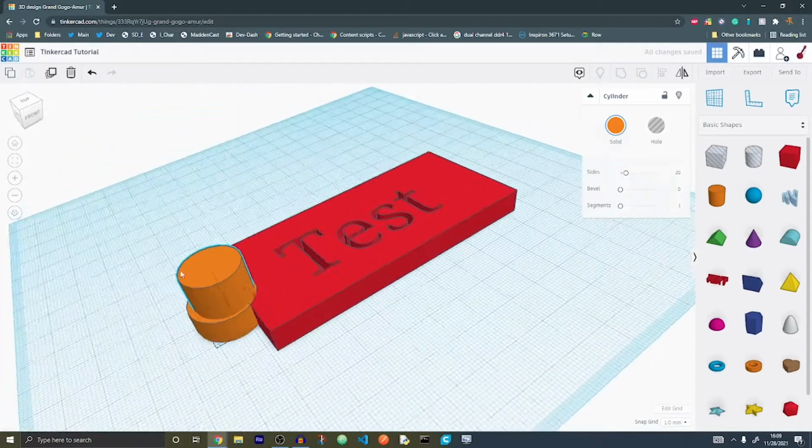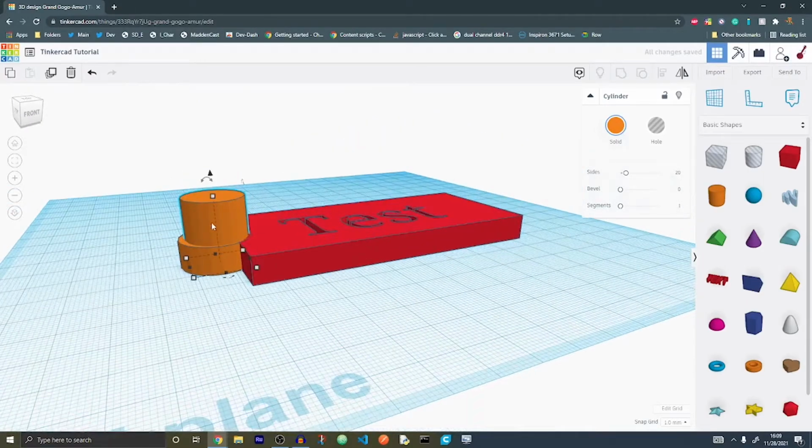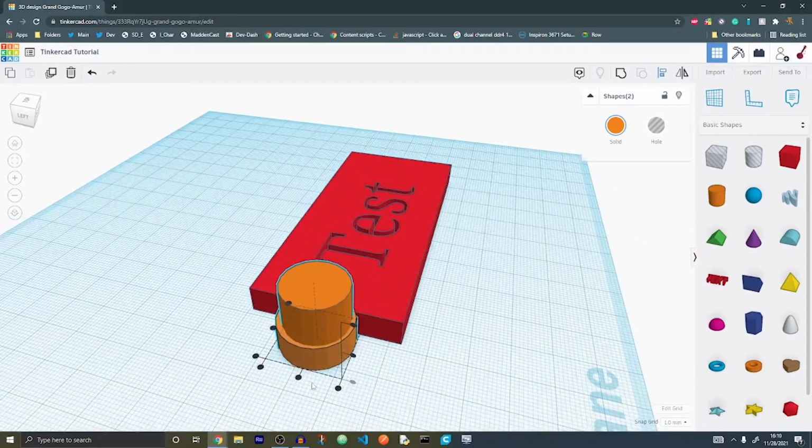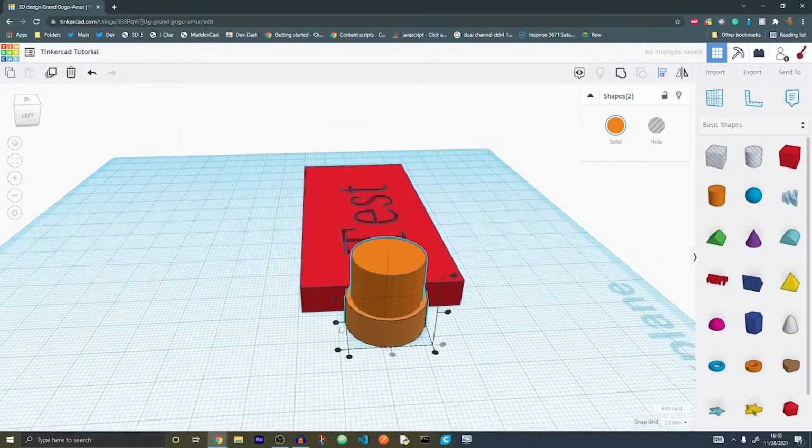This isn't going to be very perfect, the centering right now, but hold down Shift, click those, and then if you want to center it, up here you'll see a line, or just press L, and then you'll see these different buttons up here. So if you want to align it on this axis here, it's kind of hard to explain, but I'll try to explain.